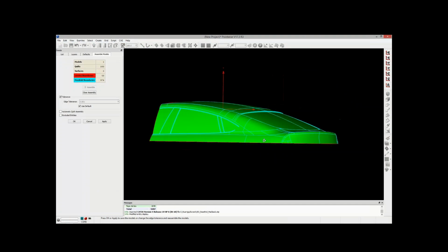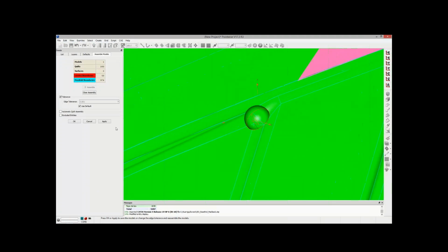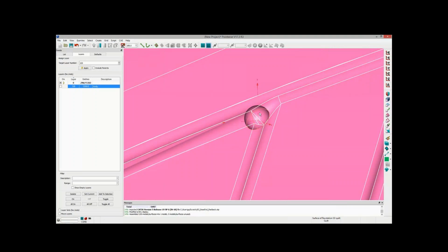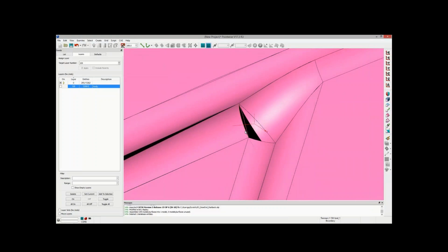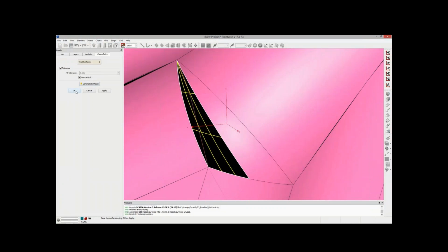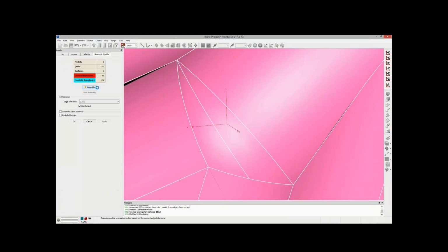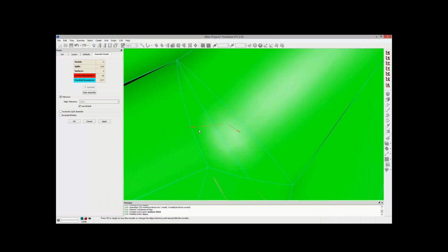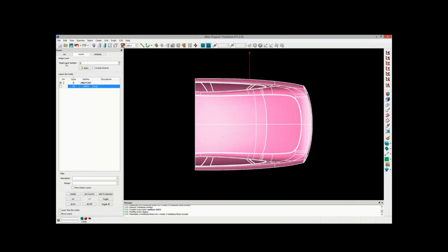Okay, and now I'm just going to inspect it to see if there are any issues on the surface, any lamina boundaries. A lamina boundary is a free edge, and I've identified this little spherical surface that was used in the construction of that fillet. So I'm just going to delete that. I don't need it. And in doing so, it pokes a hole in that geometry, which is fine because I can grab those boundaries and I can create a Kuhn's patch to kind of fill that hole and then add it back to the model definition. Okay, so this demonstrates how you can use various tools in Pointwise to clean up and heal your geometry. Okay, so now I have a watertight representation for the fastback, and I'm tucking it in its own layer,